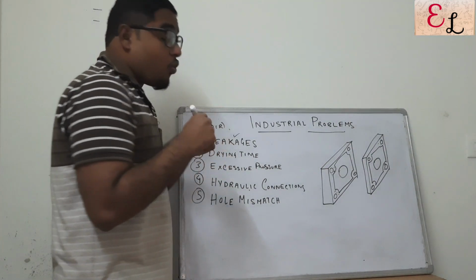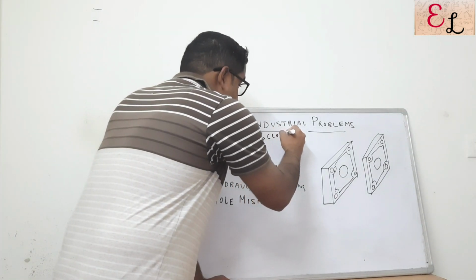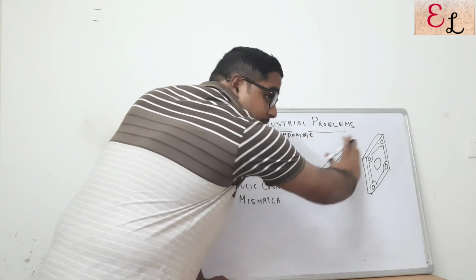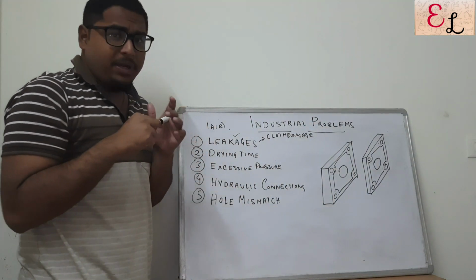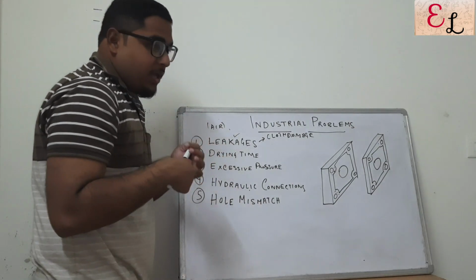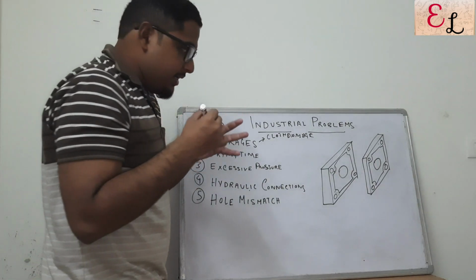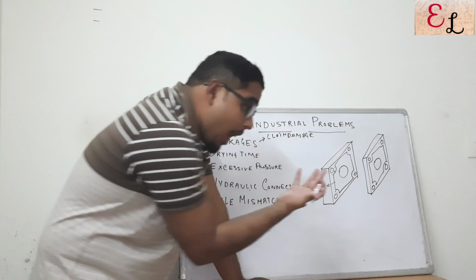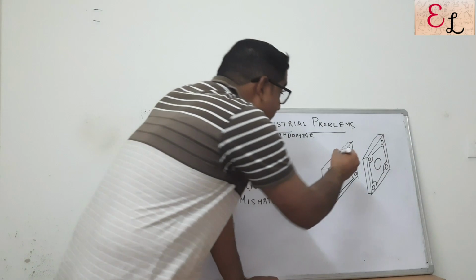Now this is very important, my friends. Understand this. The major cause of leakages is cloth damage. So if your filter press cloth right here on the filter press is damaged, what will happen? The filter press cloth is hanging, or somehow it is distorted in structure. What happens is it either pushes the liquid such that the cloth pushes the liquid out of the filter press, or it allows the passage of the liquid through the cloth.